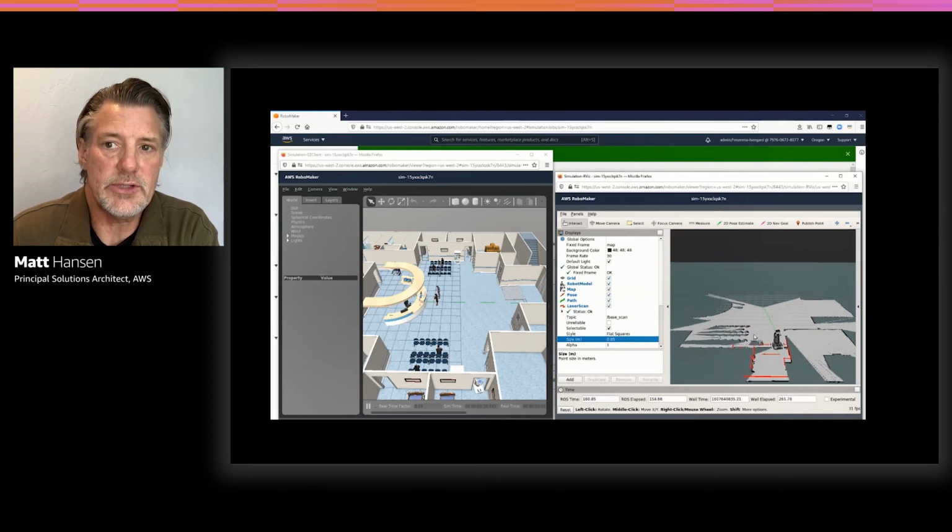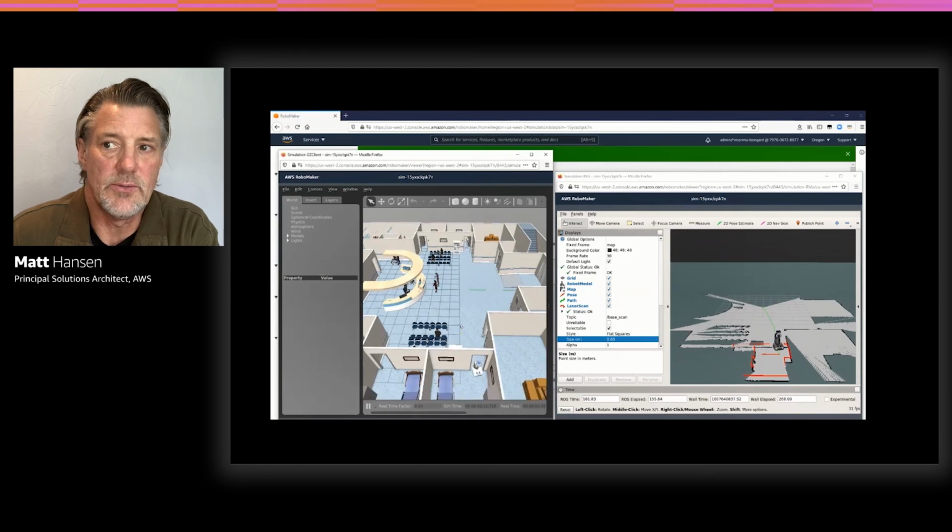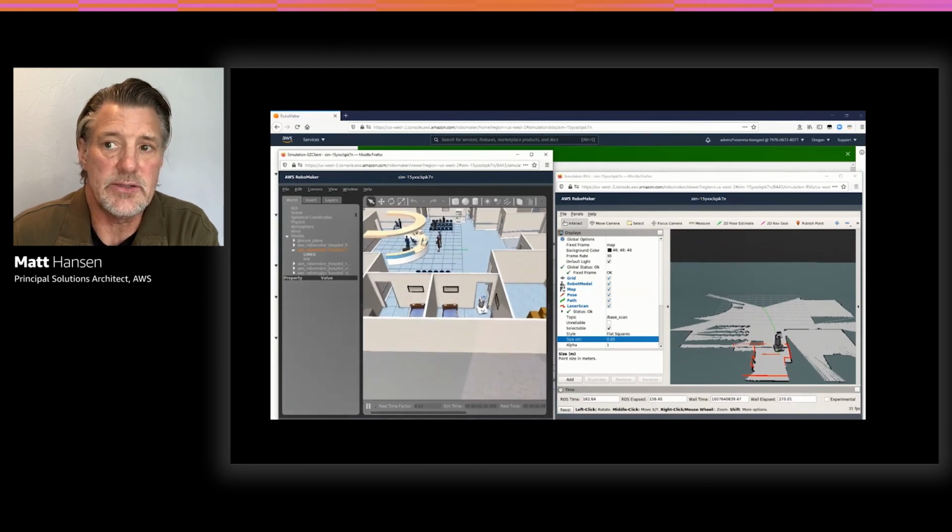As you see, we can also change perspectives to see the robot at different angles as it's moving through the doorway, for example. And when testing the robot, we would normally write a script to send a goal or multiple goals in succession to a robot and make sure it reaches those goals by checking its position via other ROS topics. This type of testing is good for validating SLAM, navigation, and collision avoidance algorithms. And, for example, ensuring that the robot doesn't get stuck in the doorway.